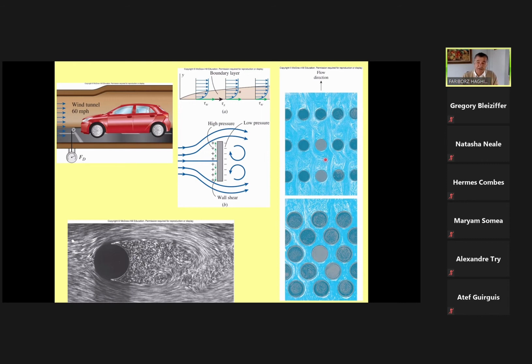Now, in the design of a heat exchanger, we need to know the value of the heat transfer coefficient. In most cases, how do we do that? It's very difficult to find an analytical solution. We can calculate it numerically, but numerical methods cannot be used every time we would like to design. Therefore, we try to use an experimental technique to find an average heat transfer for this scenario, okay?